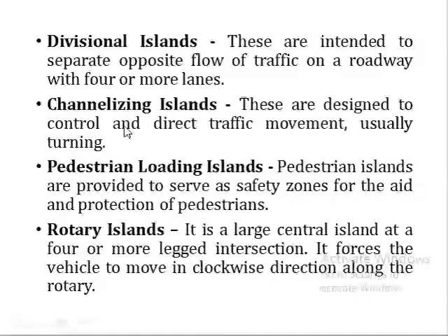Channelizing islands are designed to control and direct the traffic movement, usually turning. Whenever there is a left-hand turn or a right-hand turn, there is a channelizing island provided there to provide a separate way for the road user to turn their vehicle.